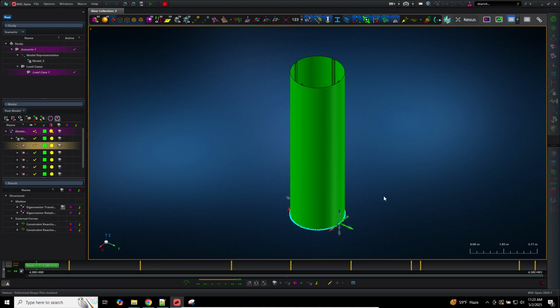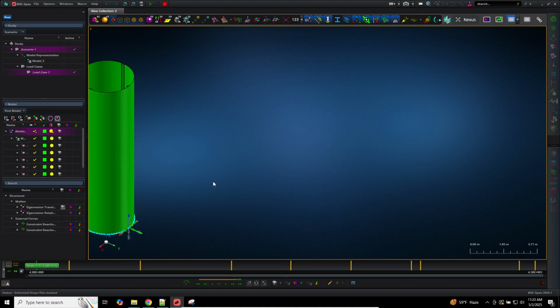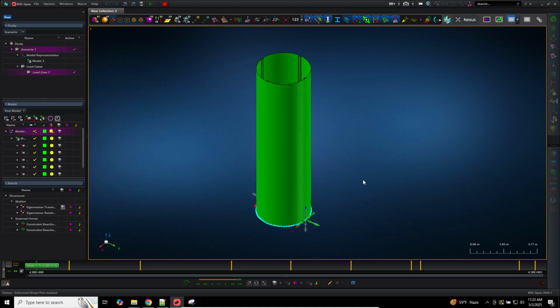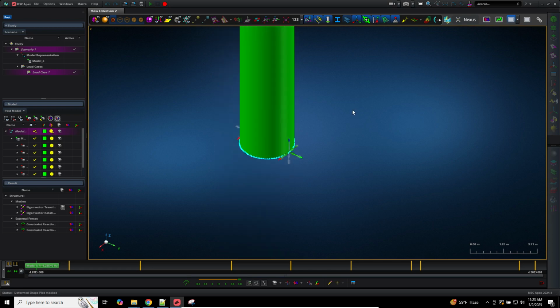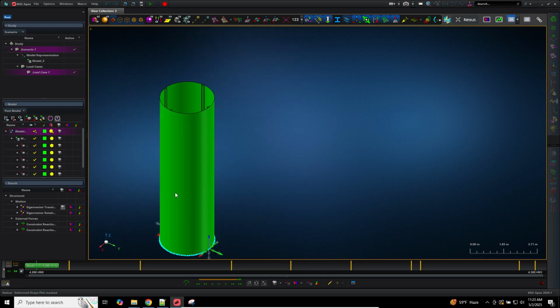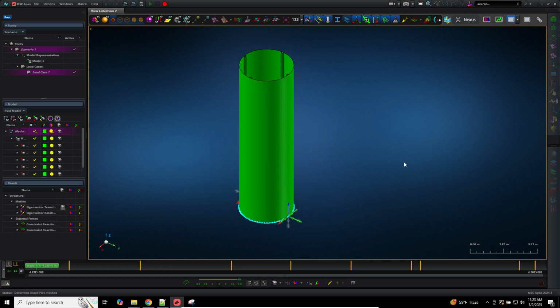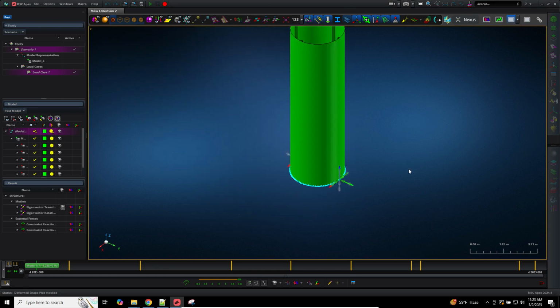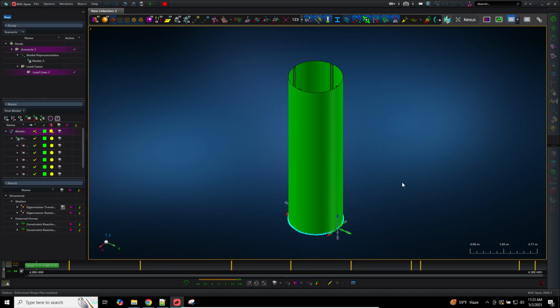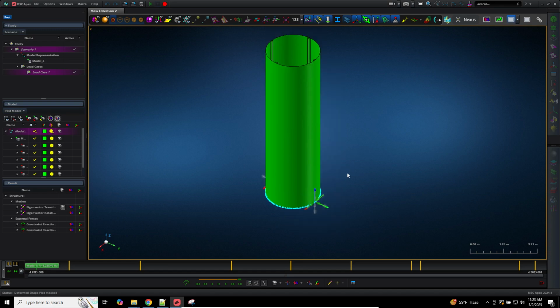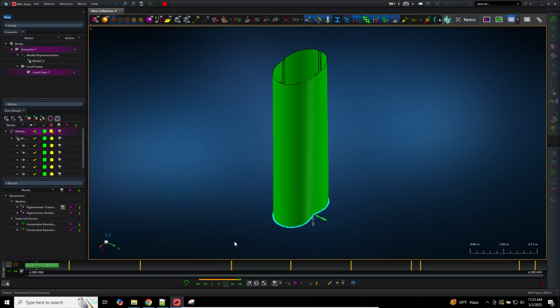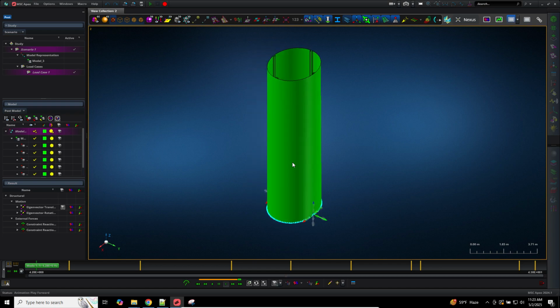What happens there is the following. When you animate the mode shape, it's going to translate vertically, horizontally, in and out. Say you had no supports, it's going to roller skate all over the screen. You're going to get those rigid body modes, 0 hertz. That's what the mode looks like. Here, this is what it looks like when you've properly constrained your model. You can see that this mode, it's not bouncing all over the place. It's pretty well supported here.